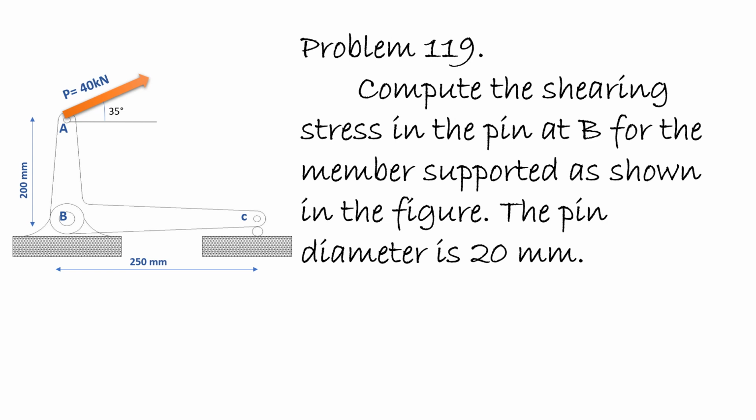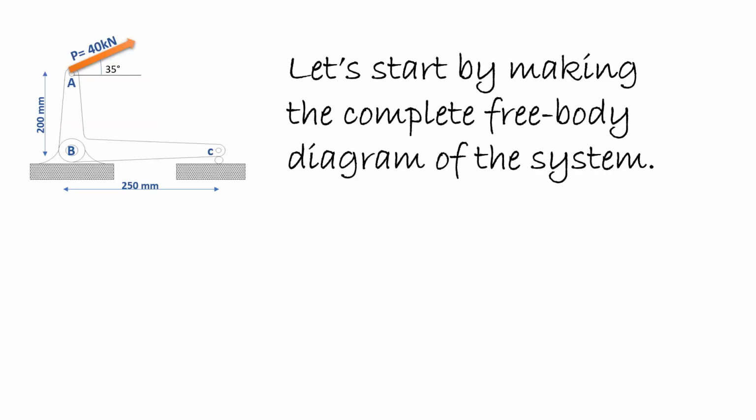So we are given the pin diameter, which is 20 mm, and we are to solve for the stress in the pin. In order for us to solve the stress in the pin, we have to calculate the reaction force acting in the pin. So let's start by making the FBD of the system.